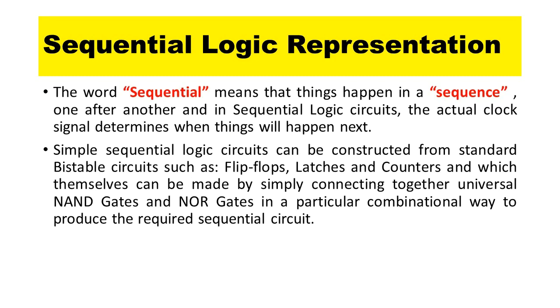The word sequential means that things happen in a sequence, one after another, and in sequential logic circuits, the actual clock signal determines when things will happen next. Simple sequential logic circuits can be constructed from standard bistable circuits such as flip-flops, latches, and counters, which themselves can be made by simply connecting together universal NAND gates and NOR gates in a particular combinational way to produce the required sequential circuit.